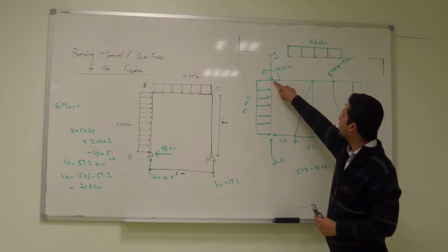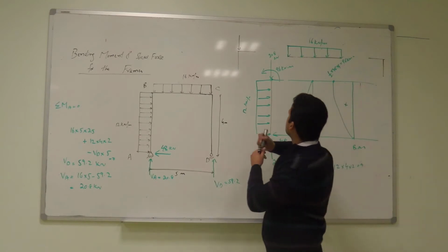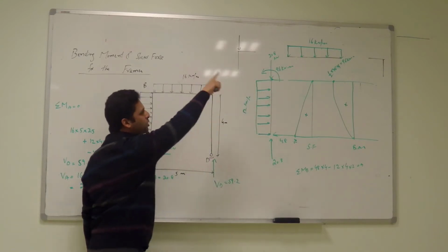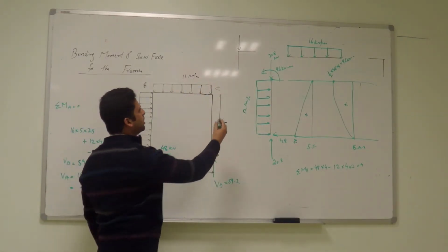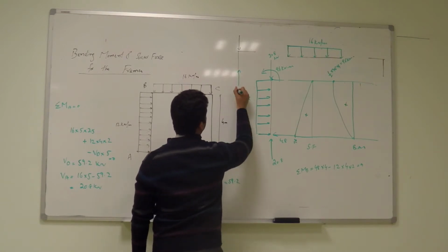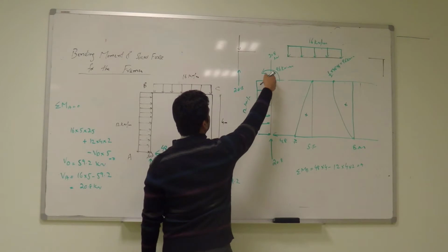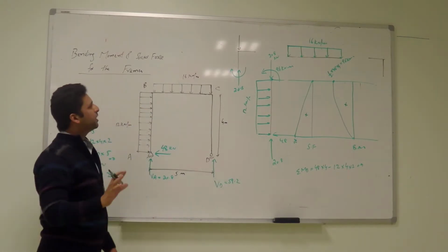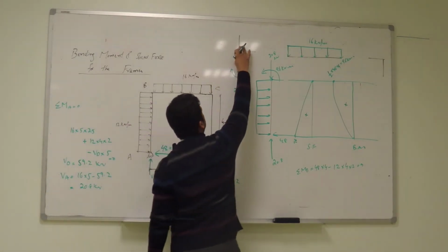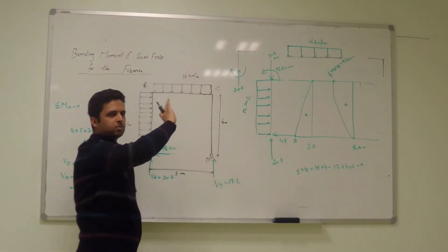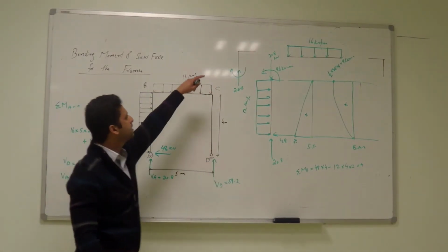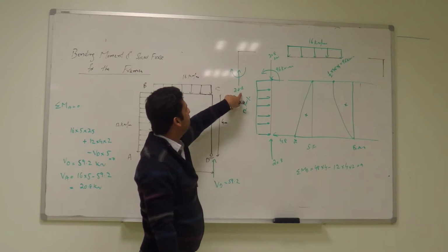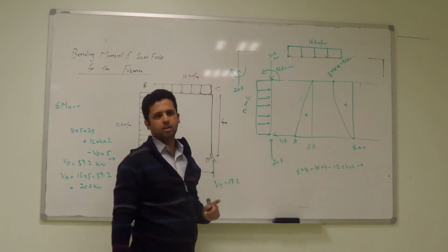So how many forces do we have here? Two forces. Now when you move to this joint, you will just show these two things but with the opposite sign. Like 20.8, and this moment is counterclockwise. Now this joint is not in equilibrium. There is no such force. If there is any force, you will apply equilibrium here. For example, if there is a force here, like 10 or 20, then you will put it in equilibrium and apply the remaining force here.